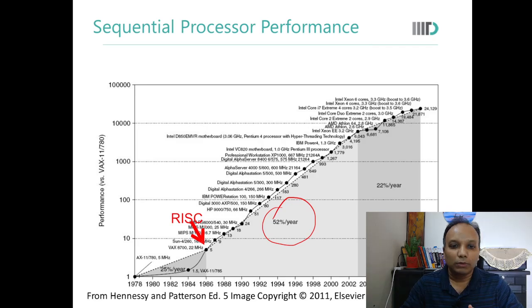They have the same number of operands, they take the same amount of time to get executed, etc. So you can implement parallelism and pipelining much better in RISC compared to its counterpart, which is CISC. CISC is complex instruction set computer, and Intel x86 and VAX are CISC processors. Anyways, we will go into that in detail in our subsequent slides.